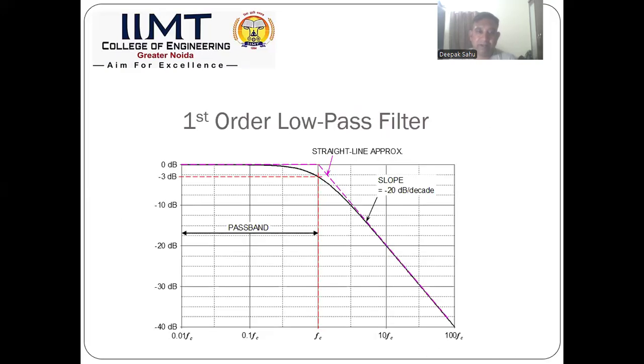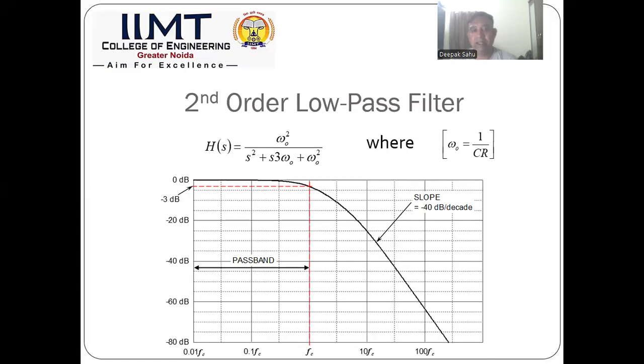But in the earlier case, where the slope was 20 decibel, that frequency range covered much more, approximately 10 times fc. So we can see here, as the roll-off factor improved, we saved bandwidth. We should not use the term saved, but have a reduction in the unwanted frequency